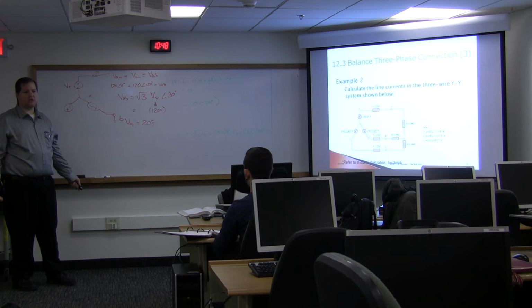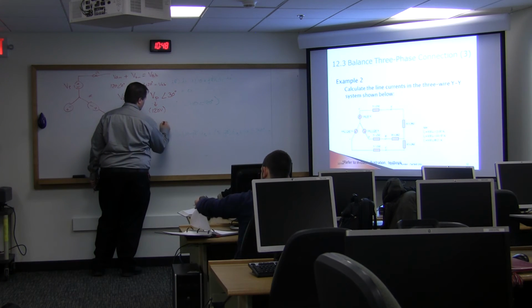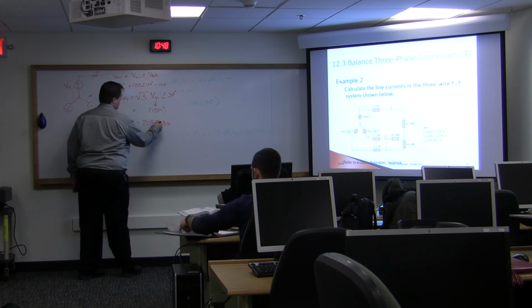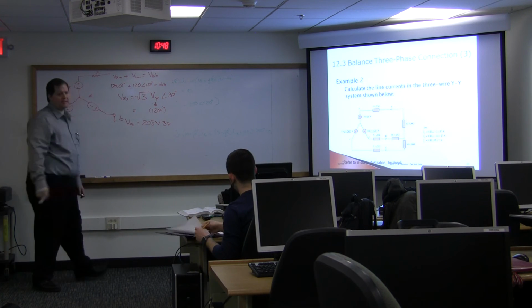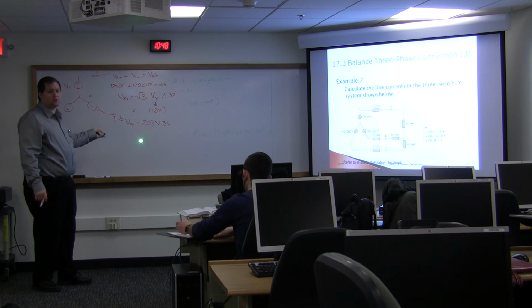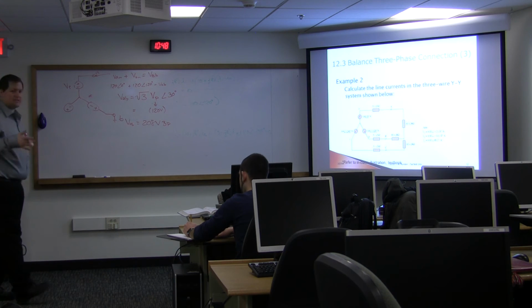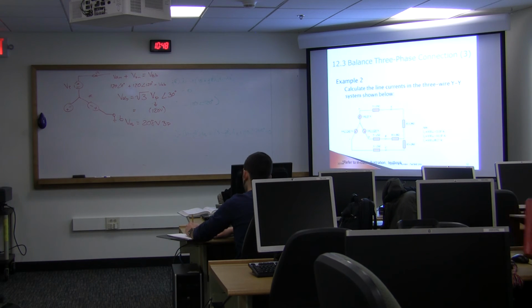And you're like, well, how do you get 208 volts? It's 208 volts three phase, and that is because root 3 times 120 is 208. And so most three phase systems in a standard environment like this will be quoted as a 208 three phase system. So you'll see that regularly.